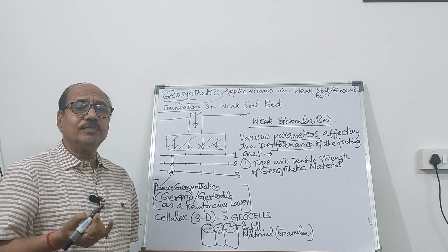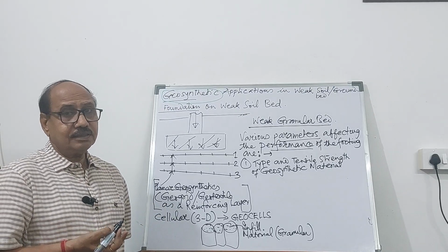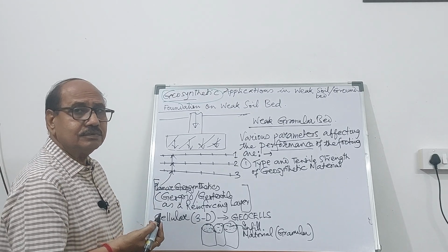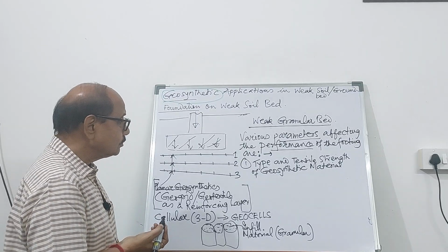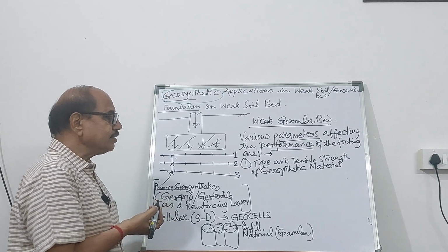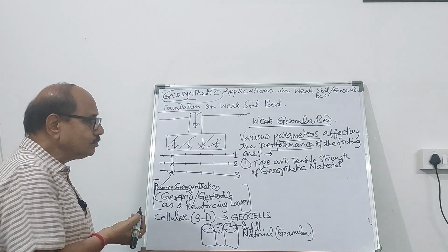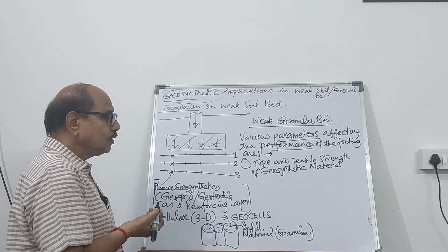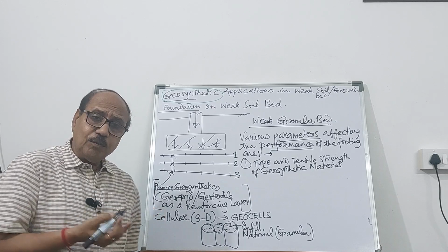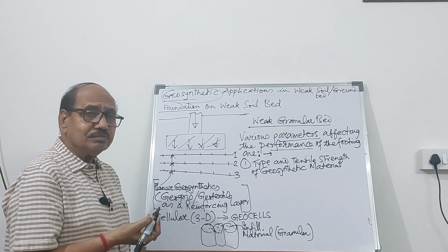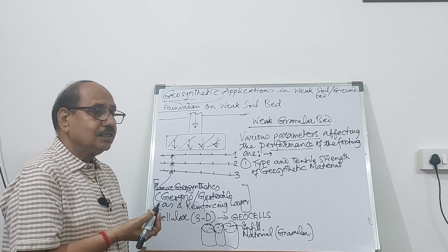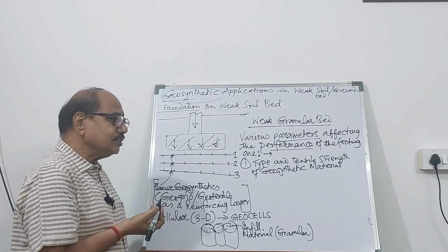There is a lot of improvement in load carrying capacity and considerable reduction in the settlement of the footing. So one thing is the type and tensile strength of the geosynthetic material. Depending upon the polymers from which it has been manufactured, that also plays an important role so far as tensile strength is concerned.